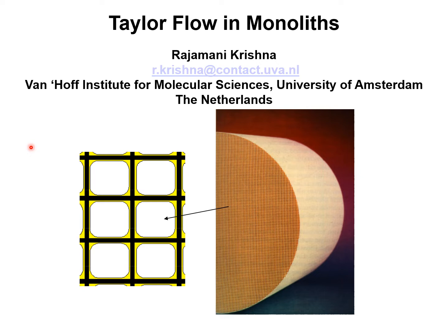These advantages of monolith reactors stem from the uniquely structured multi-channel configuration as pictured here. The advantages include low pressure drop, high gas liquid mass transfer rates, minimum axial dispersion.